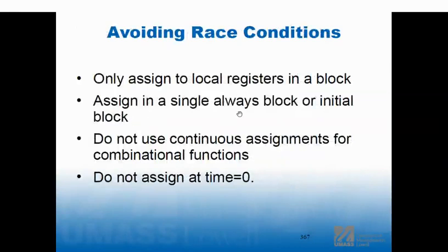So, wouldn't it be nice if we didn't do that? Wouldn't it be nice if we didn't have a case where we wrote to the same location? If you're building FIFOs, that's fine. FIFOs don't have that problem because you don't read from a location until you've completely written to it. You never write to the same location from two different places. But if you have other memories, you might have to deal with this. And it'd be really nice if you didn't, but you're not the designer, you're the verification engineer. So even if the designer didn't think they did it, as a verification engineer, you want to make sure.